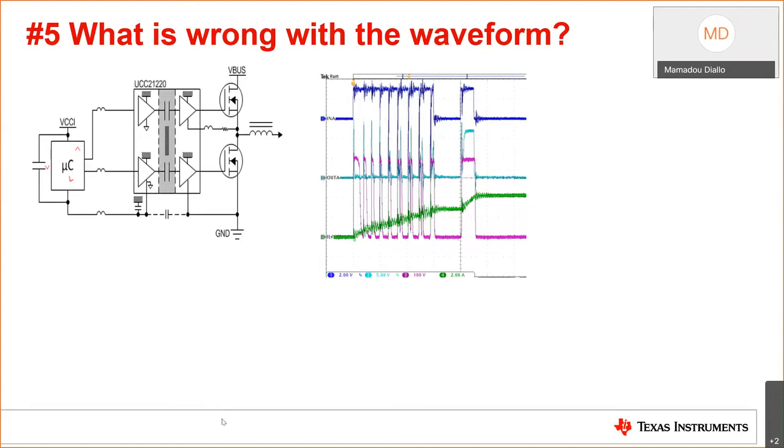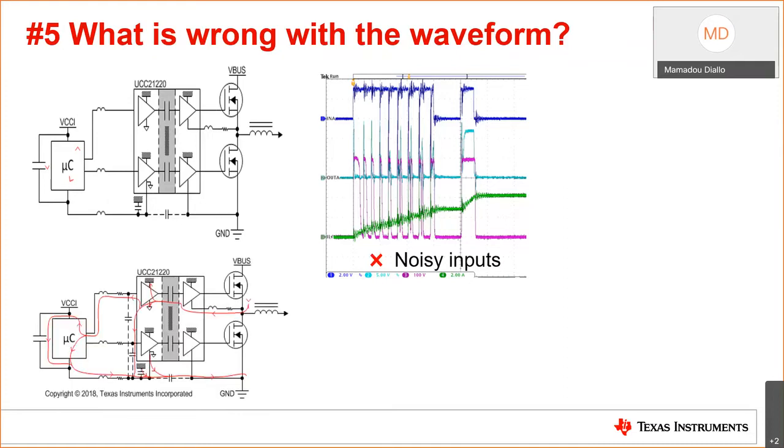So essentially, what you're seeing on these waveforms is the noise on the PWM signals, which is coupling to the power stage, causing severe overshoot across the system. During high-frequency switching applications, it is also common to encounter ground bounce due to high dv/dt and high di/dt from the power stage. This factor, combined with poor layout, could cause noisy signals on the driver's input and controller, which will couple throughout the gate drive portion.